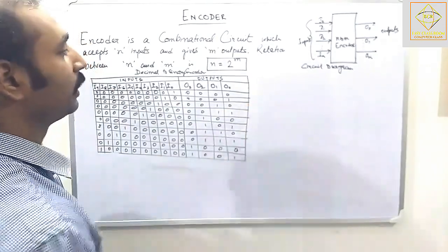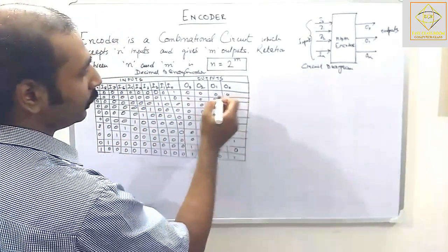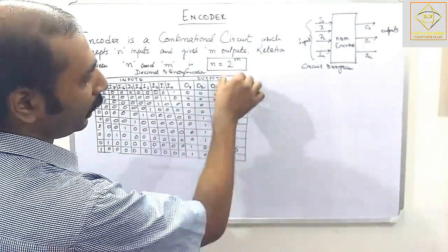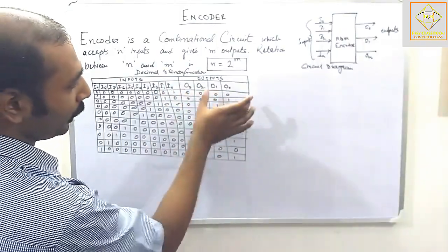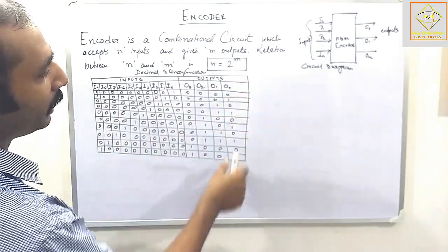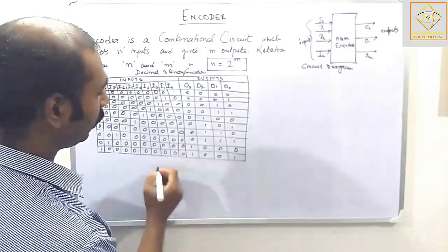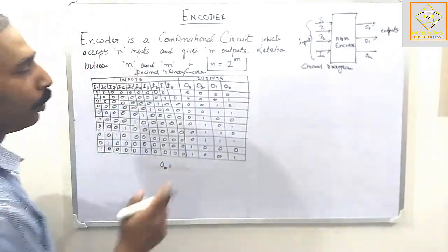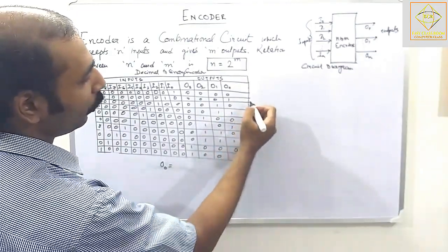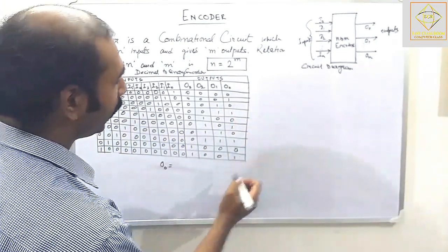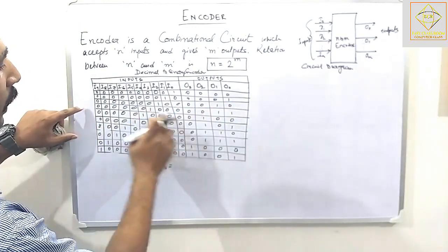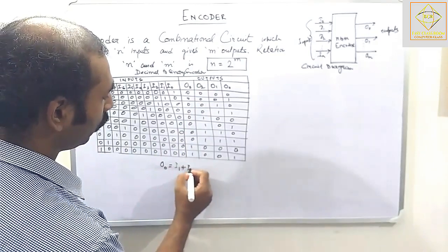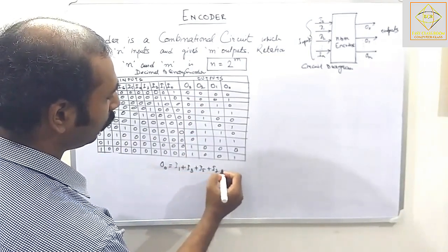So how to find the circuits from this output section? Now if we have this output as 0 0 0 0, we will send this output as O0, O1, O2 and O3, not in these formats, but in these formats. Now we have to consider these output sections. So if we consider O0, what are the high signals that we are getting? We are getting alternate signals, that is 1, 3, 5, 7, 9. So we can consider it as I1 or I3 or I5 or I7 or I9.